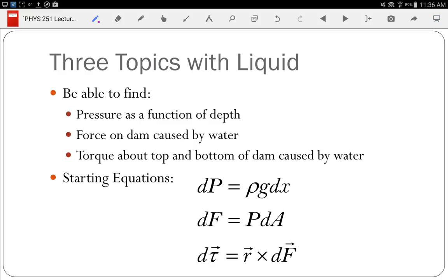But because you have a higher pressure, that's going to cause the fluid to compress a little. And so I could give you something that has you calculate the pressure as the depth increases, and you may or may not have a constant density. If the density is not constant, you would have how the density changes with pressure.